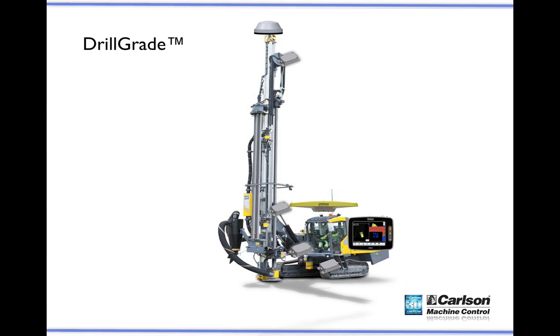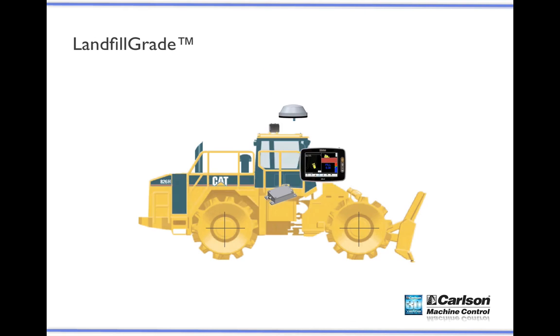We can see the accelerometers, axial sensors moved to monitor positioning on a drill. Here we have heading on the machine. We have the control box console here, and then we have an RTK position on top of the feeder. And then regardless of how the feeder is positioned, we're monitoring all of this data being fed back into the drill grade software. And again, we can either retrofit these sensors, or with the Atlas Copco FlexiRock and SmartRock, and with the HEC 3 protocol, we can use a cable, and simply Atlas Copco provides that information compatible with Carlson, and we can monitor it without having to retrofit.